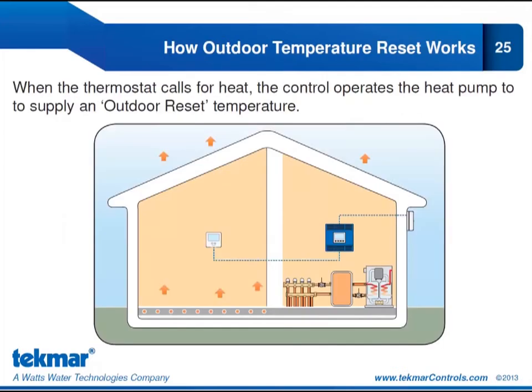So here's how it works. When the thermostat calls for heat, the control is going to operate the heat pump to supply an outdoor reset temperature. The outdoor reset control uses an outdoor sensor to measure the outdoor temperature. And the goal here is to match the building's heat loss with the heat supply. So we look at that outdoor temperature, determine what the estimated heat loss is for the building, and deliver an appropriate amount of heat. So here we have 3 of our heat arrows being delivered to the space and 3 heat arrows leaving. So we have a balanced heat delivery and heat loss.